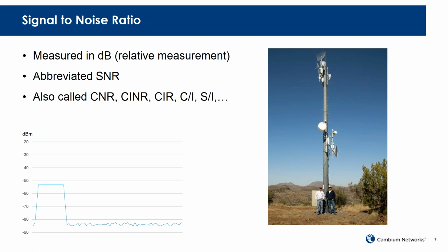And if we're going to understand interference, we also need to understand this concept of signal-to-noise ratio. And so this is a relative term. If you remember last time in the session by Dave Hensley, he introduced this concept of dBm, which is a measure of wattage. And so, for instance, you could take a dBm reading of 20 dBm, and you can directly convert that to an exact measure in wattage. And in the case of 20 dBm is equal to 100 milliwatts, or a tenth of a watt. And that's an absolute conversion.